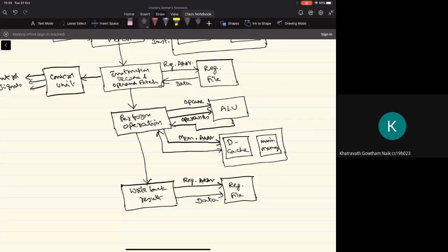The final write back stage takes a fixed amount of time because we are always writing into a register, which involves the write port delay, and we have seen that the write port is nothing but a typical multiplexer and a decoder. That does not take a significant amount of time.